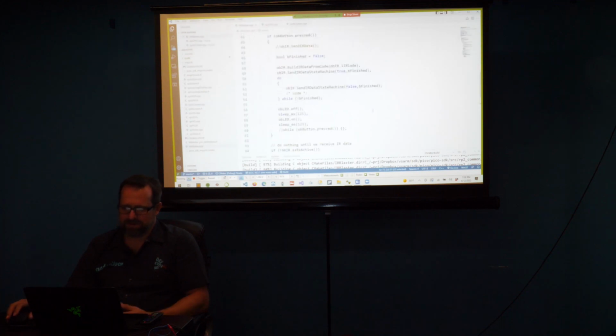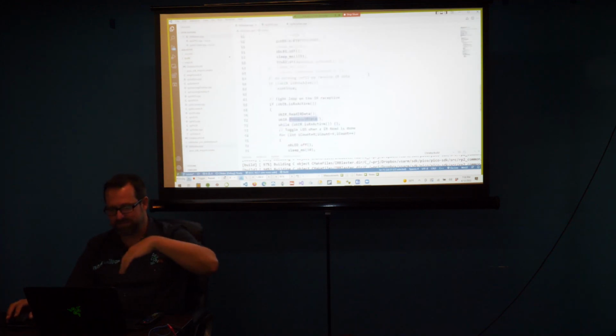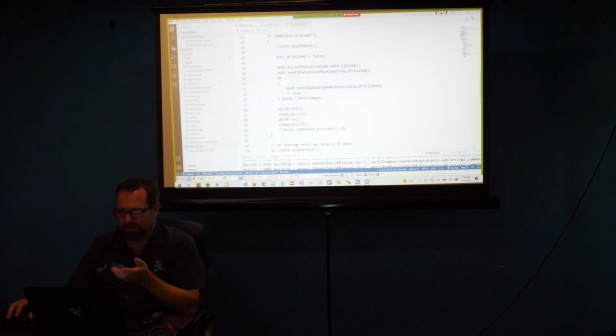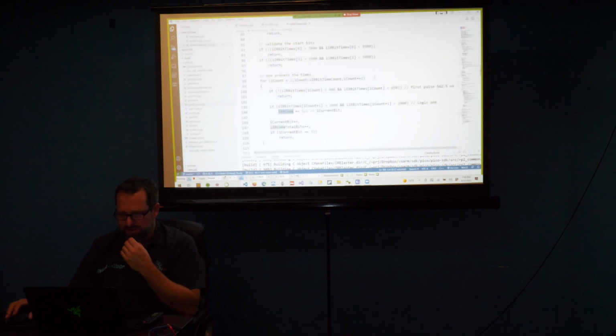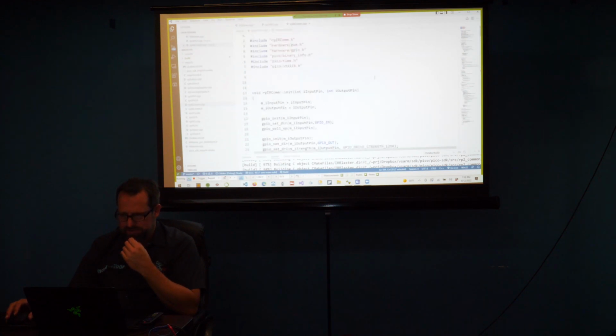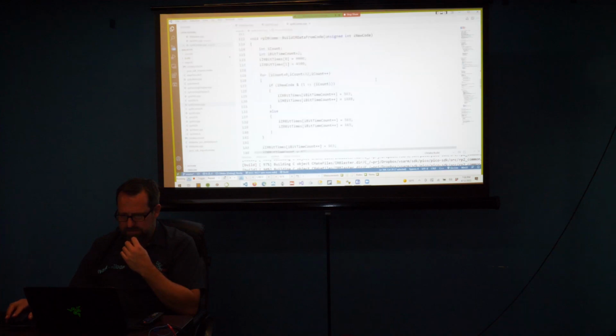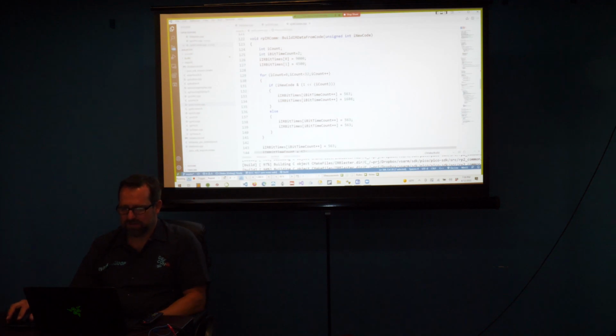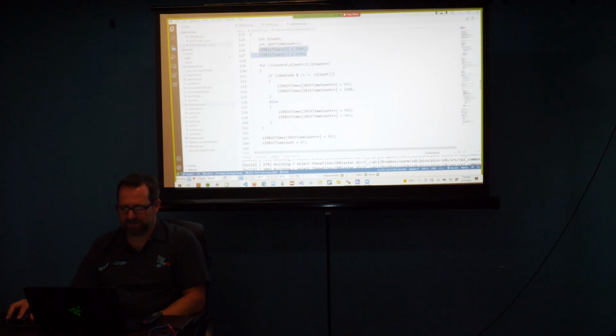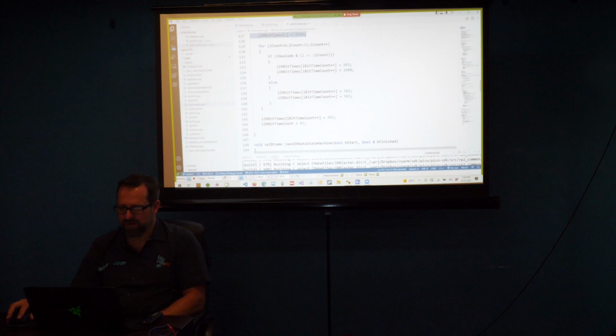And then the next thing we're going to do is the receive is done. Well, we just wait for a button to be pressed, and then we build the IR data from code. So we'll go to that back there. So it kind of just does the same thing in reverse. Takes the code, goes through the 32 bits. It builds the IR bit times. So the first one's the start bits. And then it goes through, if it's a 1, it's going to be a short pulse followed by a long pulse. If it's a 0, it's going to be 2 short pulses.